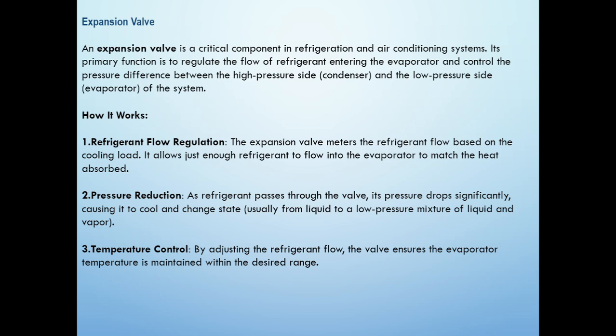How does it work? Number one, the refrigerant flow regulation. The expansion valve meters the refrigerant flow based on the cooling load. It allows just enough refrigerant to flow into the evaporator to match the heat absorbed.